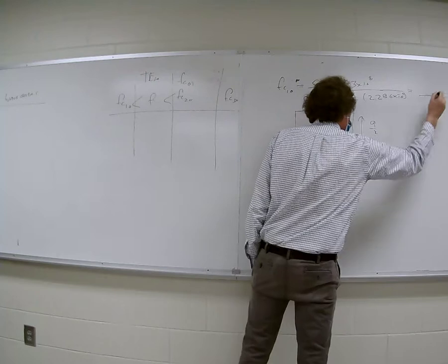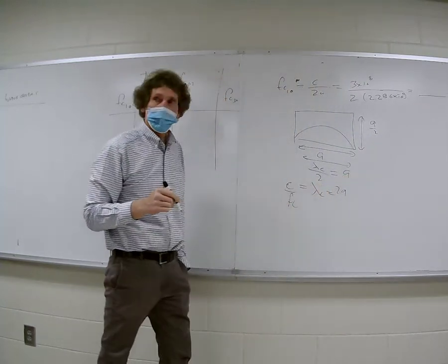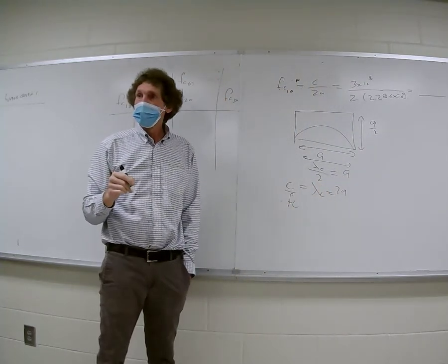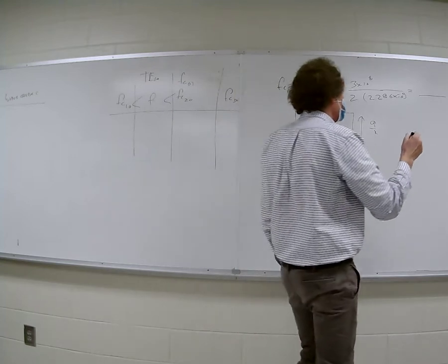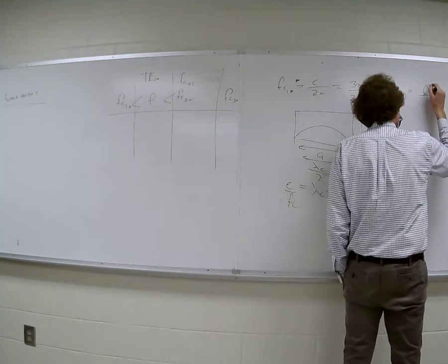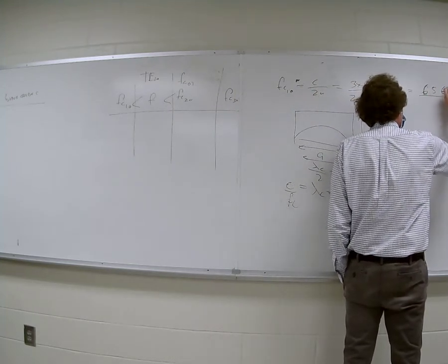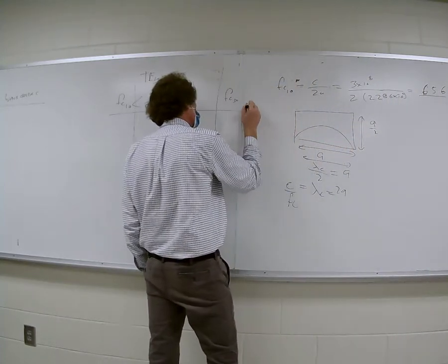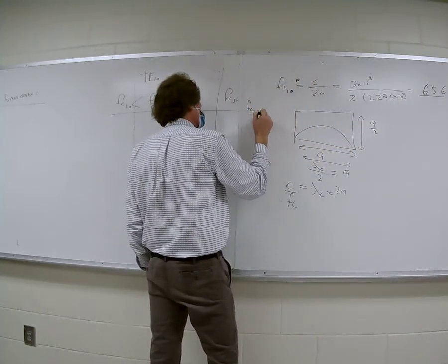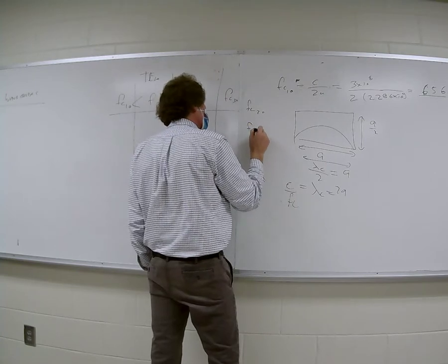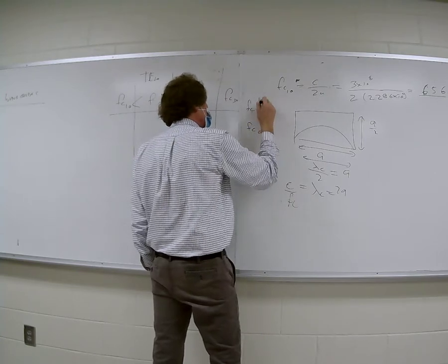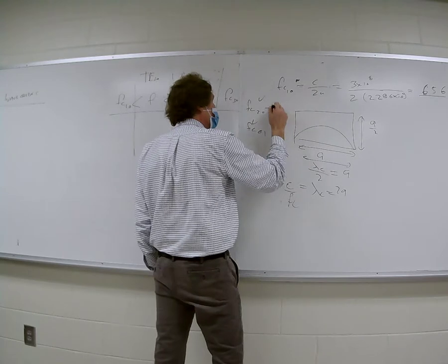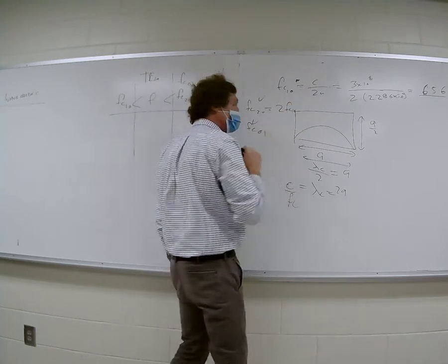You're going to go ahead and find out that frequency. 6.5. So that's right, 6.5 gigahertz. You know, the next highest frequency would be the FC20 or the FC01. In this case, it's both of these, and they're 2 times FC10. You all agree with that?